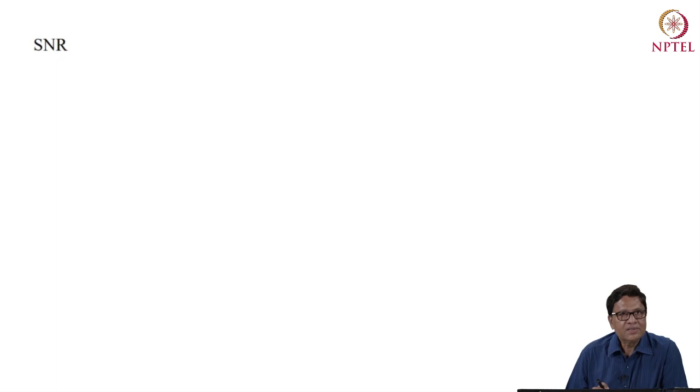So these are the noise which is there in the photodiode. Just to recap, initially there was shot noise for the photodiode, which depends on the input power, and then thermal noise, which is because of the presence of the load resistor. This was for the PIN photodiode.